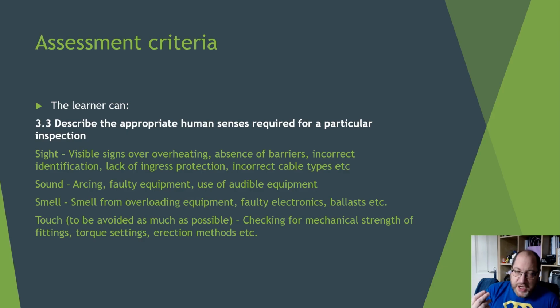Although sometimes with the installation type, it might be that we're not quite sure, and we may then go on to actually touch it. We may just try to get an understanding of a couple of conductors beside each other. So sometimes touch is needed. But it's important to know that touch should always be minimized or always be avoided as much as you can, because using touch for things like torque settings and connections, etc., there's a risk of manipulation of conductors, cables coming out, but there's a risk of shock. So always avoid touch.